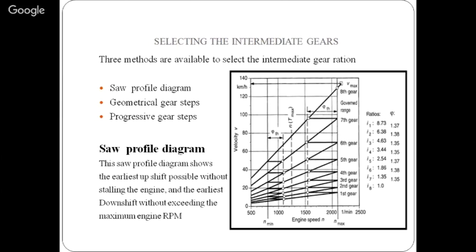How will it overspeed the engine? Suppose I am in first gear. This is my speed. Suppose I am in 6th gear. This is my speed. When I wrongly put 5th gear with this speed, this will be the engine RPM. When I wrongly put a downshift, with downshift my engine RPM increases. If my engine RPM increases, then there is a maximum engine RPM in the engine.